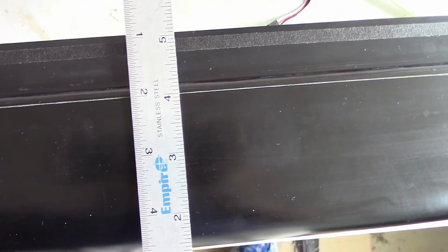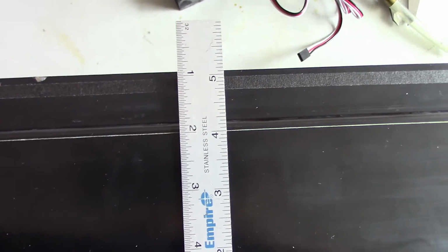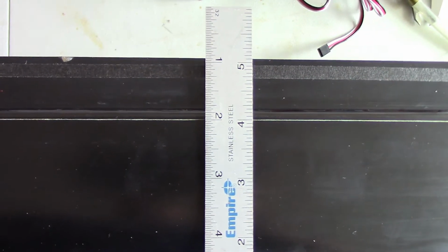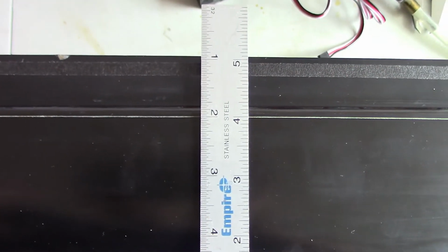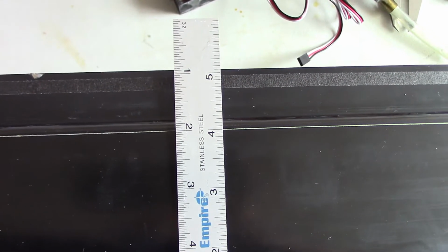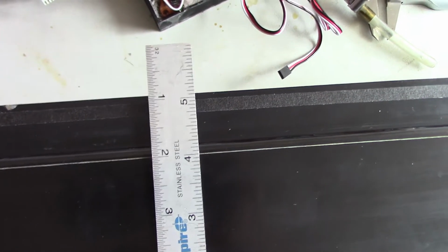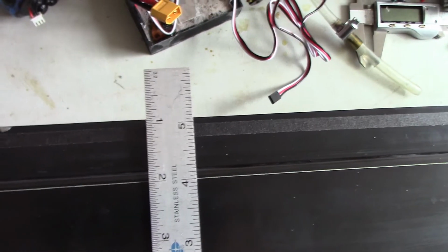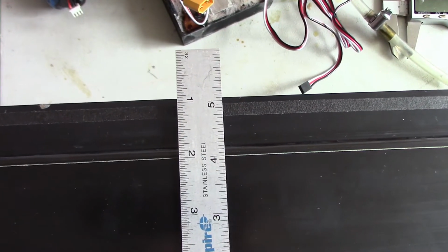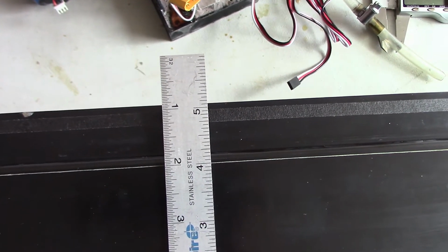So what I'll do is I'm actually going to mark it probably at more of 1 1/4 inches. That's going to give me a little bit of buffer, so maybe once I build the boat and I drive it around, maybe I find out that the way I built it is heavier than I want it to be. When it gets water in it, that's going to decrease the freeboard. So maybe at the weight I build it, if it's too heavy, the boat might be too sluggish, might not be responsive. So I might want to lighten it up a little bit.